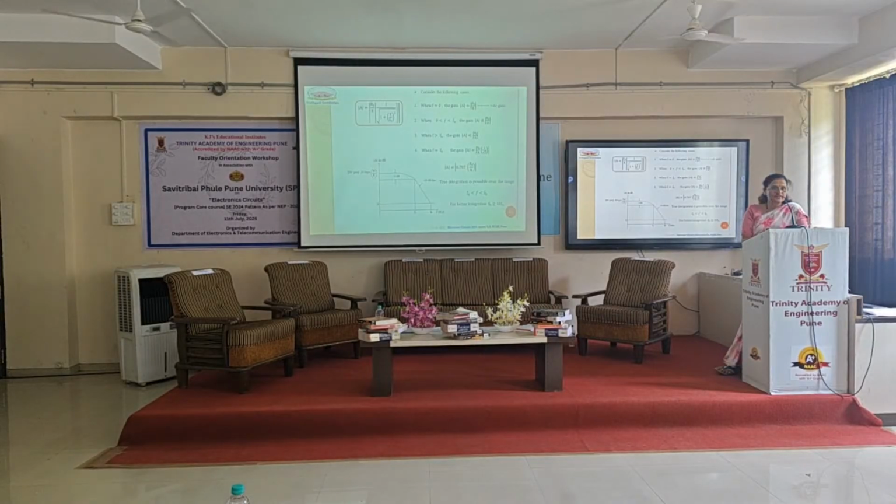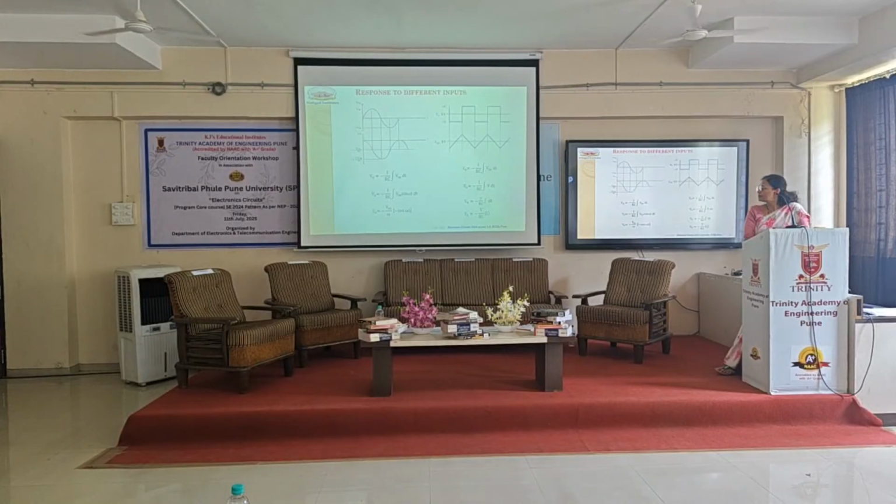Now once the design gets completed, students are supposed to observe the operation of the same circuit as an integrator. Means apply the square wave at the input and observe the output working as an integrator. So one has to take care about the frequency of the signal.